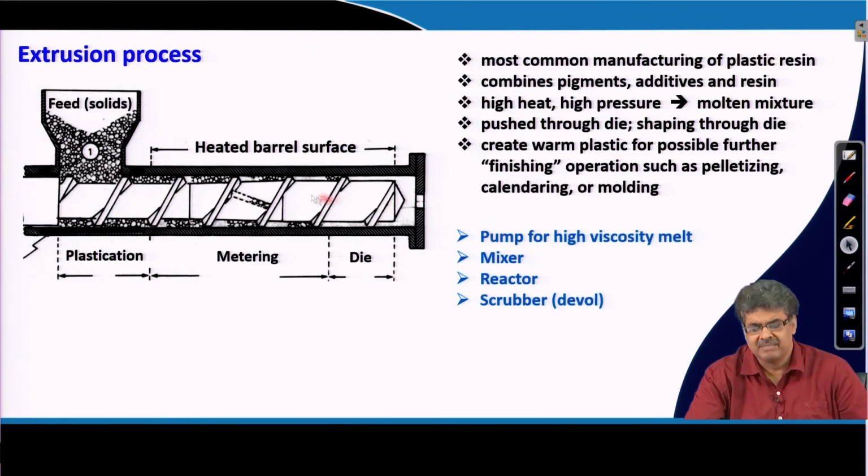So, it basically pumps the high viscosity melt, and it also mixes different ingredients. You can actually use this also as a reactor if we use materials which react with each other, which is not very frequently done, but we can do that. We can use this extruder as a reactor also, and it can be used as a scrubber as well.